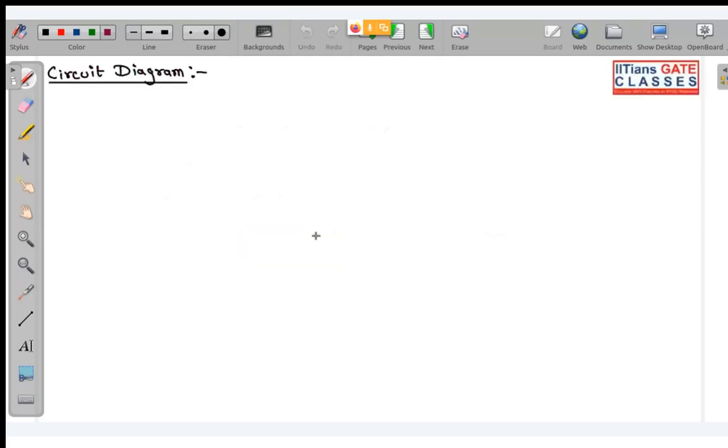Okay, fine. Now we have the circuit diagram. So how do we actually make this? So for sum, we got it as A XOR B XOR C in, and C out. Raju, no need to write yes, sir. Okay, you don't need to write that, just write Y or N whenever I ask if you have understood or not. And C out we got A XOR B, C in plus AB. Okay, so now we need to construct this.